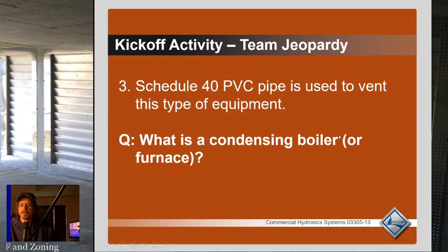PVC pipe. Here's an interesting note. The funny thing about PVC pipe being used for venting is that it is approved by the equipment manufacturers, but it is not approved by the piping manufacturer. So I don't know if they're still doing it, but there was a really hard push for a while there for that polypropylene venting piping, because the PVC pipe manufacturers were saying, we don't care what you do, but we're not warranting our pipe. So in other words, the equipment manufacturer has to take the responsibility for the listing when you're using the PVC pipe for it.